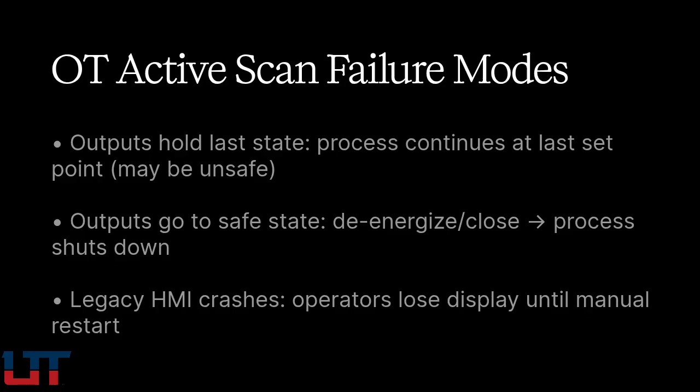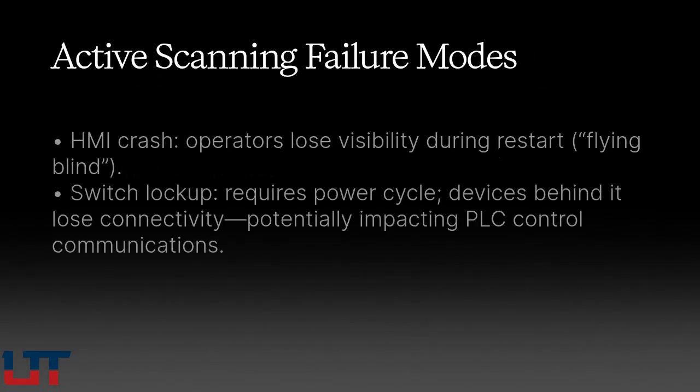A legacy HMI application crashes and requires a manual restart. During the restart window, operators have no display. If they're watching the process through the HMI exclusively, they're flying blind. A managed switch becomes unresponsive and requires a power cycle. All devices behind that switch lose network connectivity simultaneously, potentially including PLCs that depend on network connectivity for their controlled communications. A safety-critical process triggers a protective shutdown because the control system becomes unavailable during the scan.